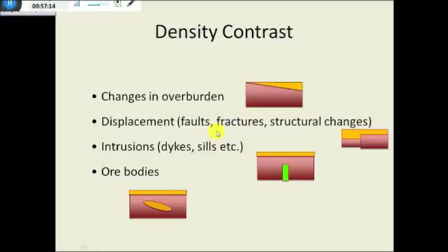Overburden is the rocks at the surface that are quite weathered. It can be soil. It can be rocks that were there originally that have just been broken down. You can see this orange is your overburden. Sometimes the overburden is the same thickness anywhere you go. Sometimes it increases in one direction. Underneath this is your harder rock. Because this stuff here is broken down, it's the unconsolidated rocks we saw earlier, the soils and the clays, so it's got a much lower density than the red underneath.